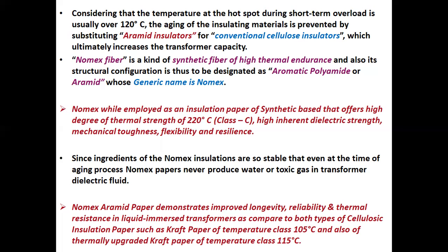Nomex aramid paper demonstrates improved longevity, reliability, and thermal resistance in liquid immersed transformers as compared to both types of cellulosic insulation paper such as Kraft paper of temperature class 105 degrees centigrade and also of thermally upgraded Kraft paper of temperature class 115 degrees centigrade.